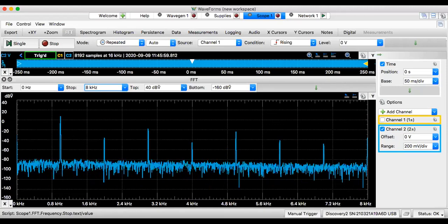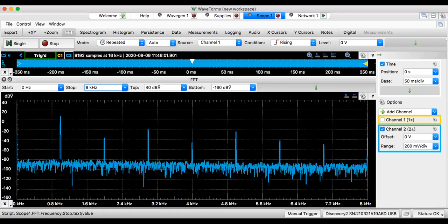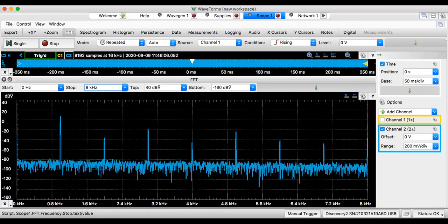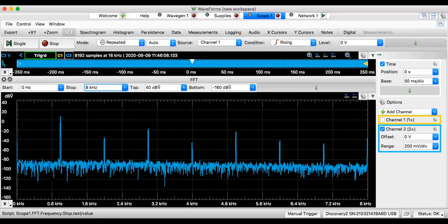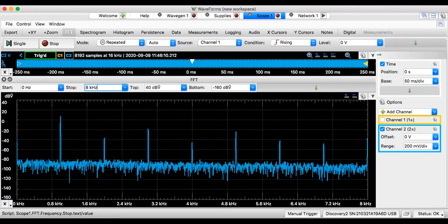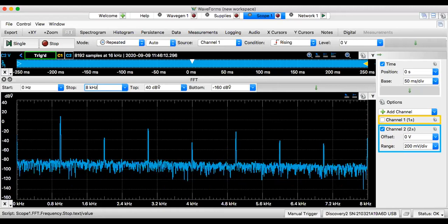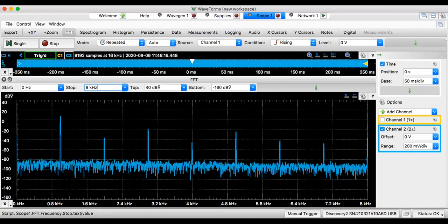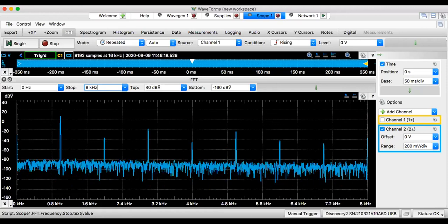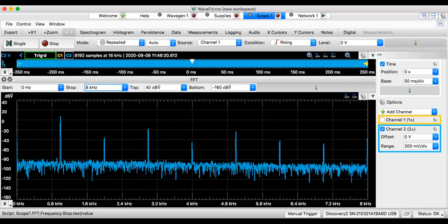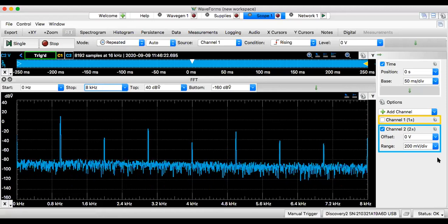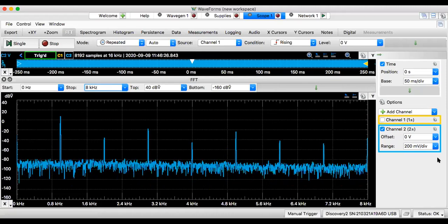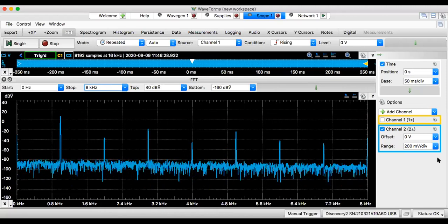In the real world, when your input signal, which is 1000 hertz, passes through this amplifier, not only do you get 1000 hertz, you get 2000 hertz, 3000, 4000, 5000, 6000, 7000, 8000 as outputs. It keeps going on forever. So those energies all add up as total harmonic distortion.